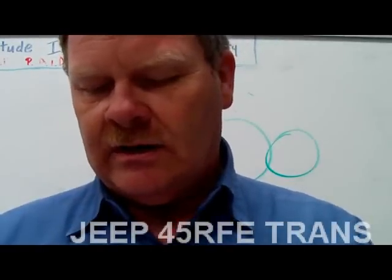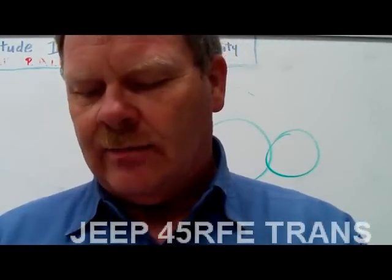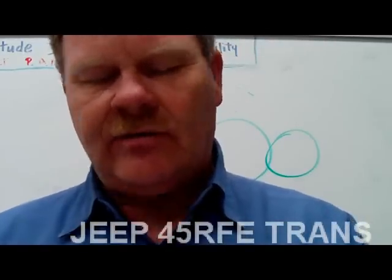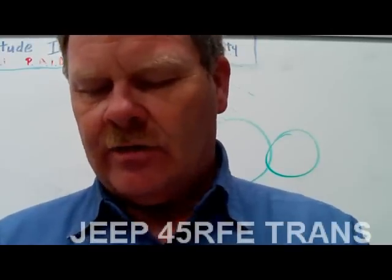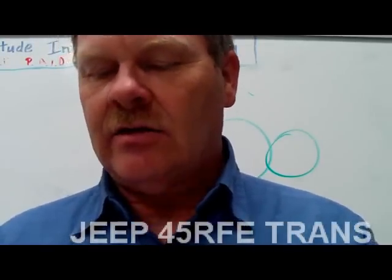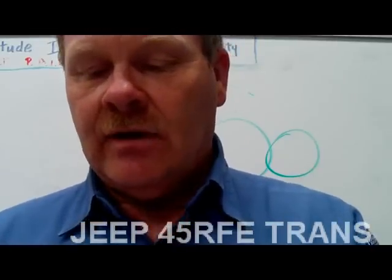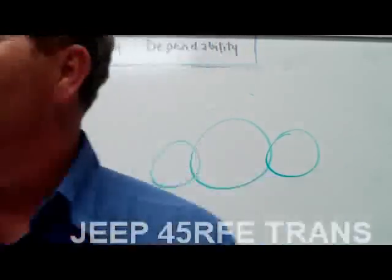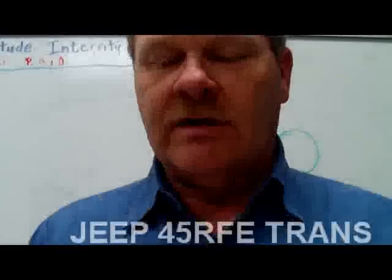Okay, so we're going to look at the clutches. Located behind the fluid pump is the input clutch assembly, and that consists of underdrive, overdrive, and reverse clutches. Further back in the transmission, we've got the fourth and second holding clutches. The lower reverse holding clutch is near the rear of the transmission. To achieve the different gear ratios, it applies different combinations of two clutches at a time. That's interesting, isn't it? Two clutches at a time.